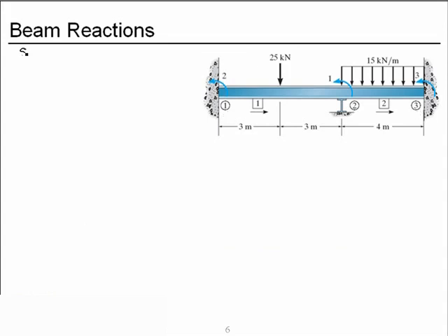And now to assemble those element stiffnesses to make the structure stiffness matrix. And we'll denote that one by capital K. So it's the element stiffness from element 1 plus the element stiffness from element 2. And this addition is by degree of freedom number. So for example,